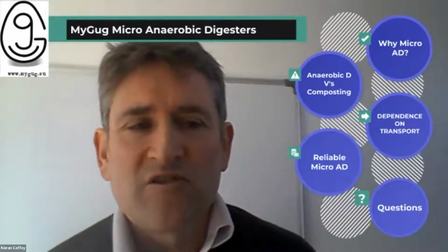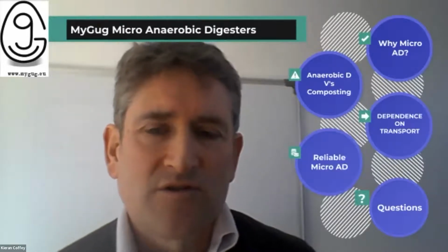Okay, I think we had a similar question from James about the integration into the existing gas cooking system, so that we have covered. Question from John: is the MyGug commercially available? And John is asking, do I size it on the cooking gas I want, or the food waste available? And then he's asking, again the similar question many others have asked, can I add non-food, so grass or offcuts to it? So no, you size it based on the food waste that you're generating.